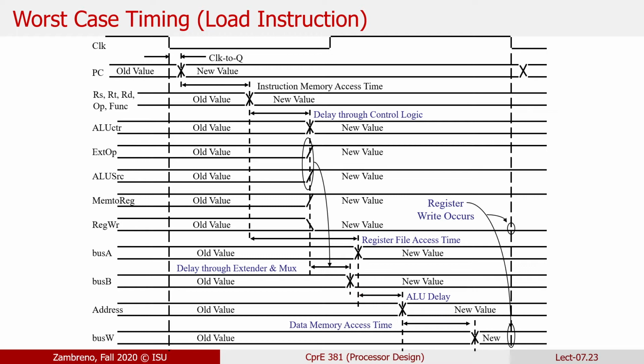When we get to the point where we're then synthesizing our design, that timing information then gets annotated and associated with the individual components that we have there. And I showed it very briefly last week, you can do a post-synthesis simulation or even a post-place and route simulation, which would use the lower level components and their actual timing delays. That will let you see your critical path as you're actually simulating the design. For our purposes, being aware of it is sufficient, not actually being able to see it.